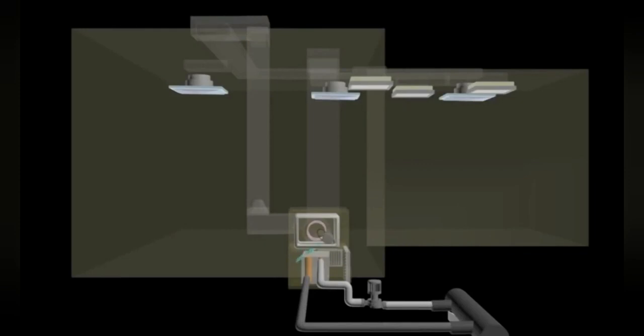For the airflow system, it is operated using an auxiliary fan which creates the air cycle from the room and mixes it with fresh air from the outside to the air handling unit and returns back to the room. The type of fan used is a centrifugal fan powered by a motor and connected through a belt.